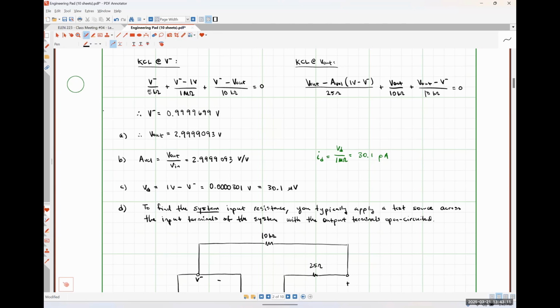So I'm going to put a homework assignment up about this where I want you to specifically find that error, but it's going to be on the order of 1% tops kind of thing, even for very poorly designed op amps. So I'm talking about open loop gains of 1,000 or something like that, and output resistances of kiloohms. It's still only going to introduce 1% or 2% of error.